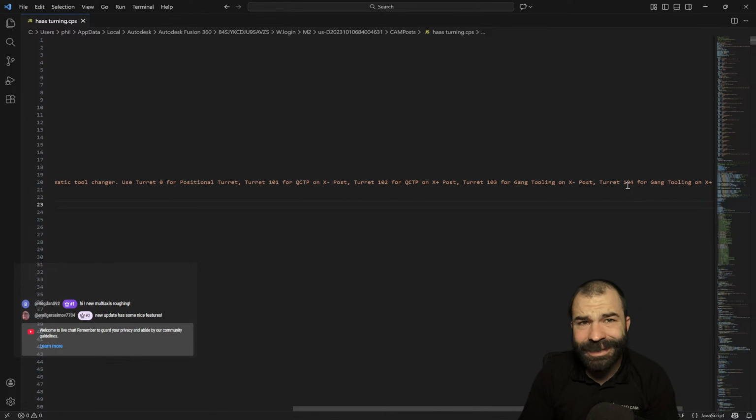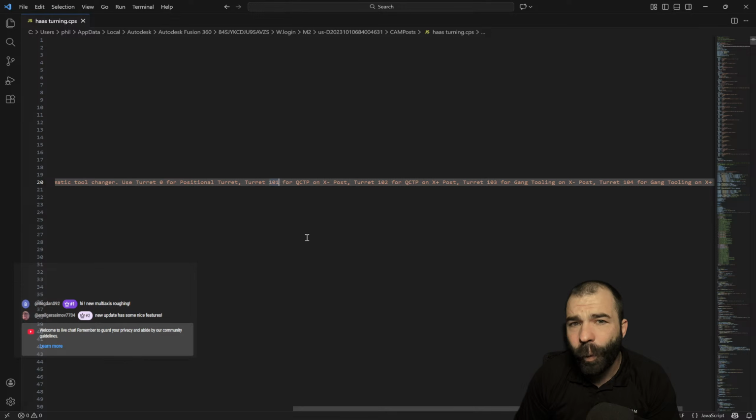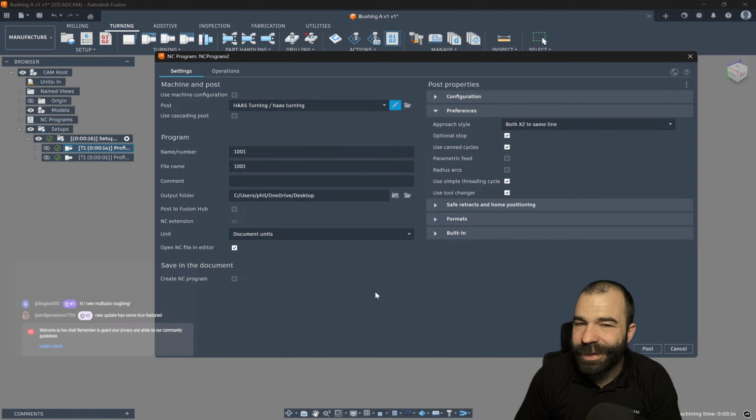And again, we have a gang style video on this. Guys, go watch that video. It's a great video at the end of the day. But again, the idea is 101 to 104 is going to control whether or not we're using a gang style holder or we're using a turret, a quick change post, things of those natures. Now you can use both of these in conjunction in the same setup. Now you can't do it necessarily on the same tool.